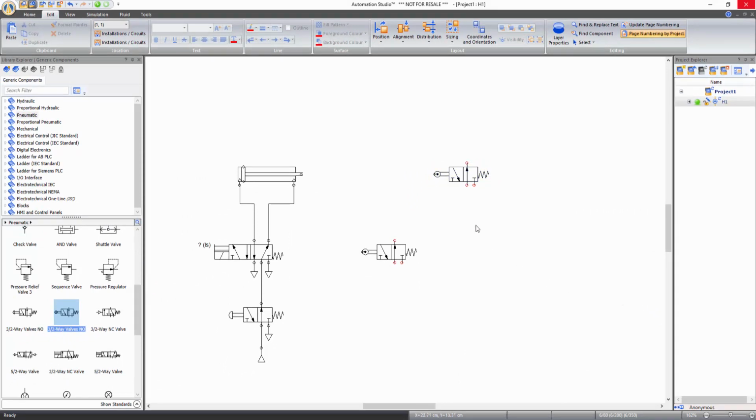To visually adjust the component layout before doing connections, click on a mechanically piloted directional valve, then click on position function in the layout tools and select rotate left 90 degree. Then from the same menu choose flip vertical.